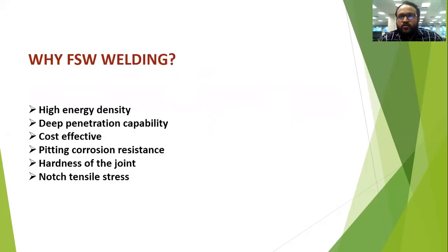So to join both the austenitic and ferritic steel, I chose friction stir welding. There are some reasons behind that. The first reason is high energy density, and the most important thing is cost effectiveness. And finally, friction stir welding gives a strong metal joint.